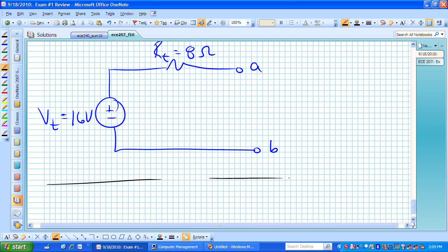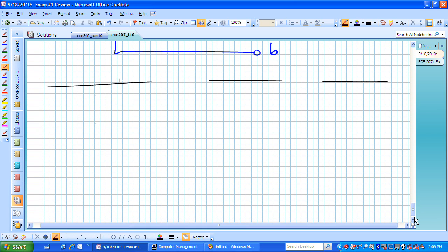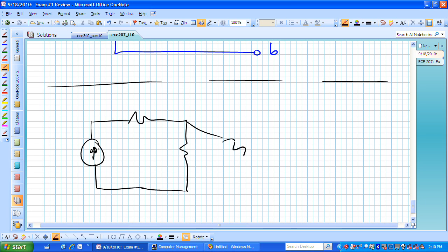As an additional piece to that problem, if you didn't want to solve for the short circuit current and you've now found, let's say, the Thevenin voltage, you could actually find the R equivalent by zeroing the independent sources that are present in the system. In this case, here was our circuit, there was our current source, we had a 10 ohm resistor, another 10 ohm resistor. We had another resistor that was at a diagonal. We had a horizontal resistor and a vertical resistor of 24.